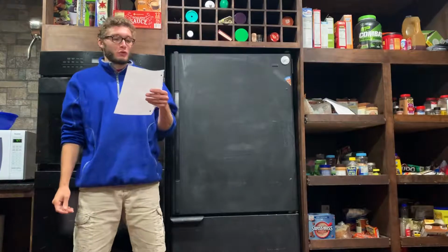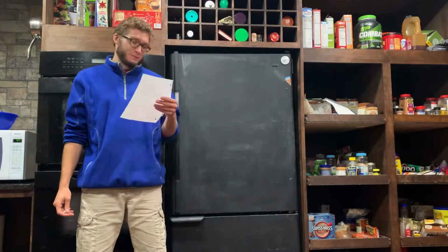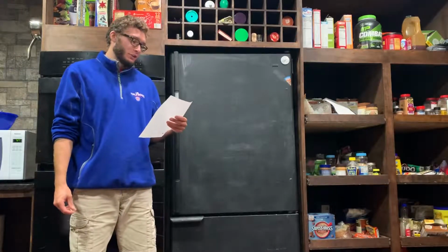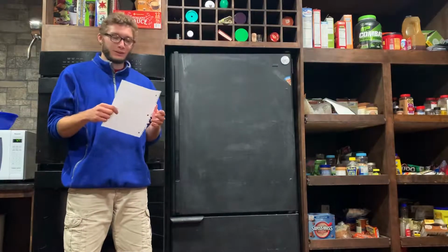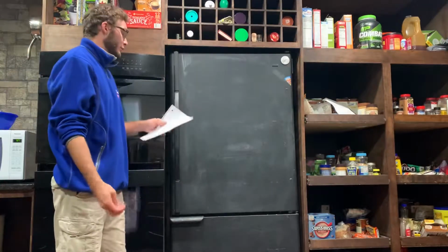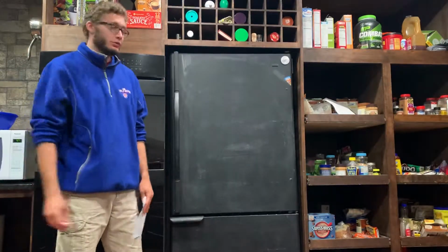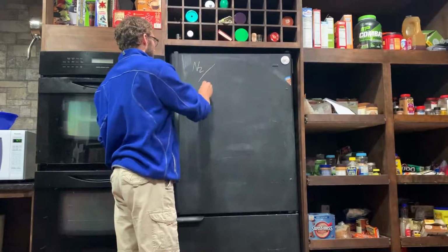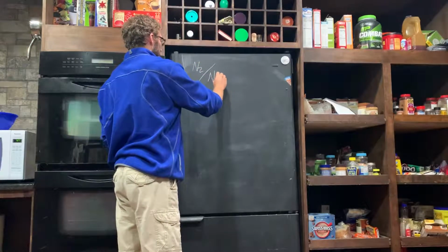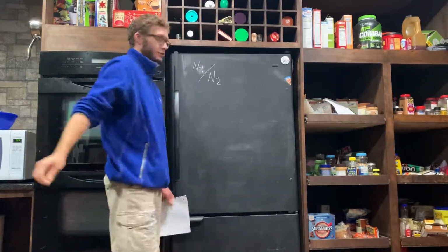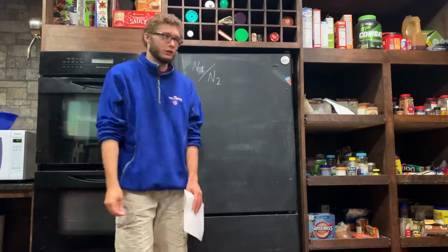Okay, this is lecture 3, gears. The main function of gears is to change ratios such as speed and torque, and to change the direction of rotation. This is done by using the gear ratio, which we usually calculate using the number of teeth of gear 1 over the number of teeth of gear 2, or vice versa, depending on what exactly we're trying to calculate.